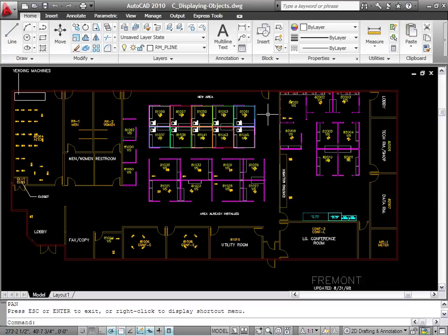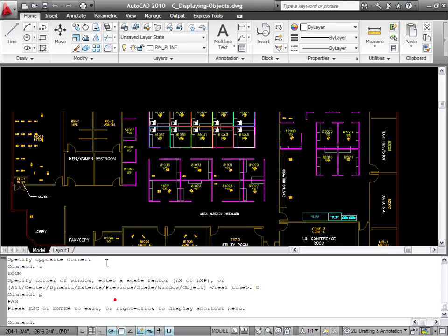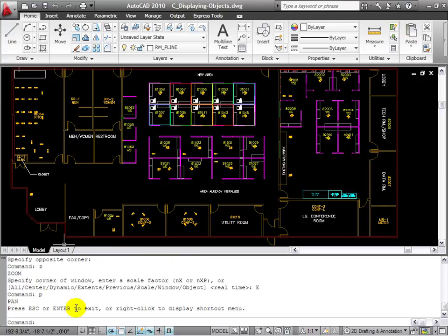So as you can see, in AutoCAD, you would be the master of the software. You are giving the commands to the software to do the things that you want. Whenever you put commands in AutoCAD, you can see the commands showing in the command line. This is the command line. Whenever you want to zoom, you just call the command. The zoom command would be Z, the first letter. If you make sure this is the command that you want, spacebar to continue.